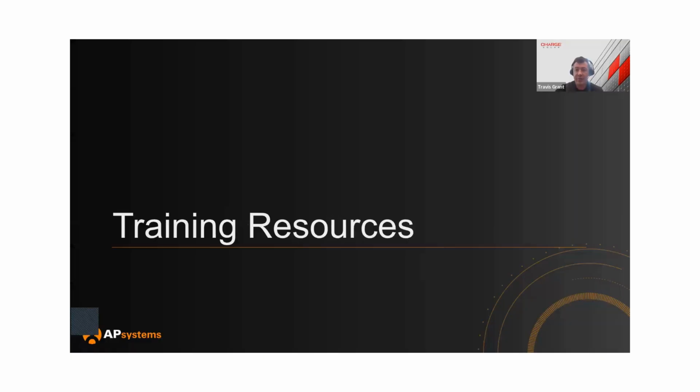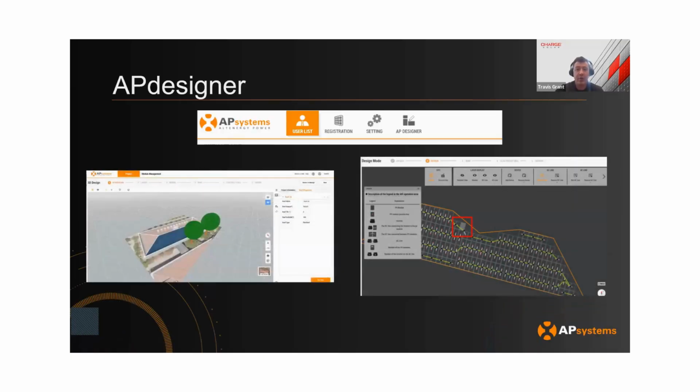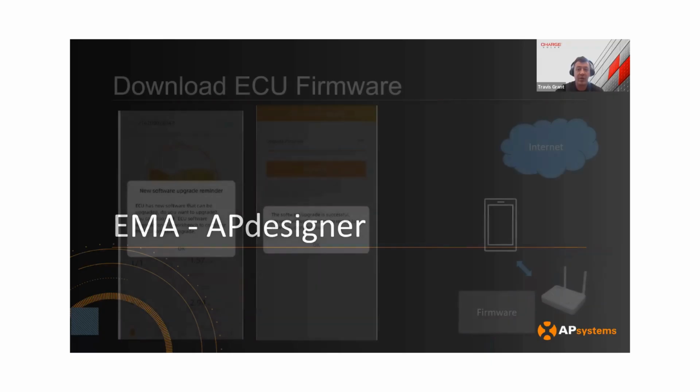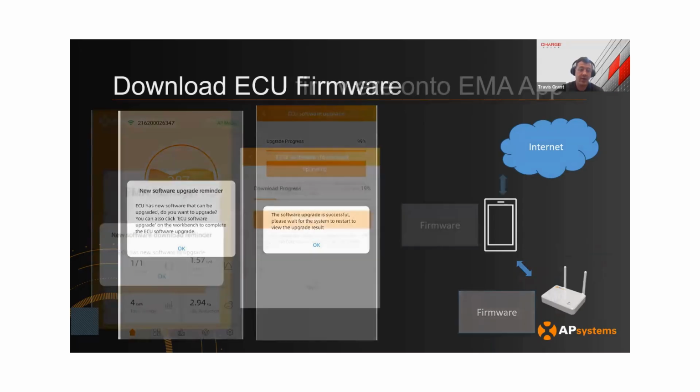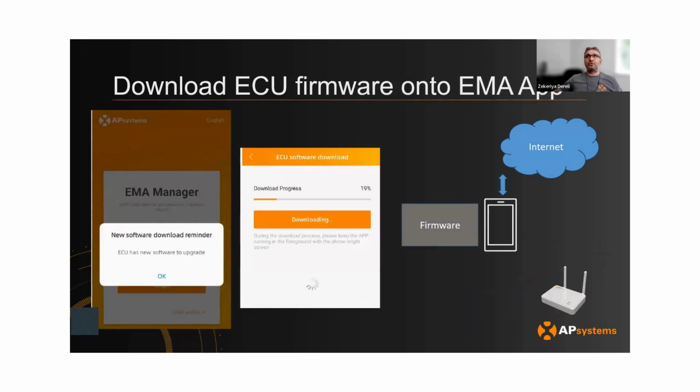Yeah, so the first one was from Jason Wilson, who wants to know if you can hook the ECU-C to a 347/600 volt three-phase service in Canada. Well, 277 line to neutral and 480 line to line is the max. There's a 10% threshold for the max, because your line voltage could be 10% higher, but that's pretty much the limit. 480 plus or minus 10% line to line is the limit.